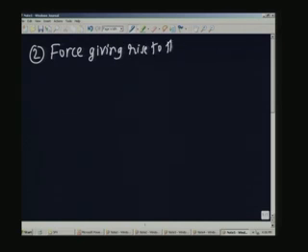Second force, this is the force which is bringing about the change. The liquid in the manometer is oscillating only because there is an external stimulus to do so. This is given by the force due to the pressure, and that can be written as P into A. This is the pressure, so this is helping the H to increase or change.